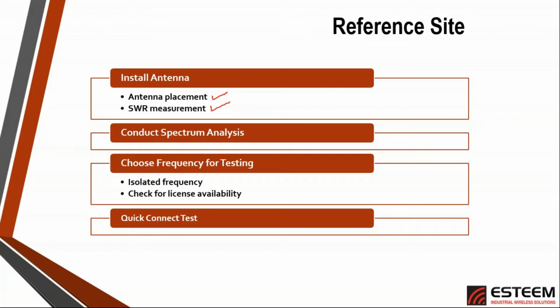Now, licensed frequency bands are a little bit easier that way, because you can go to the FCC website and find out what is available for that particular application and what users are in that area. And the best part is they have some very good search tools on that website. You can put in a location by longitude and latitude, and then say, give me all the transmitters within this frequency band within a 20-mile radius. And it'll produce a report on that. It's very, very helpful.